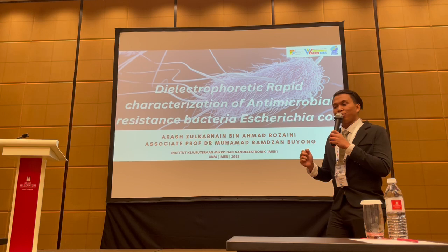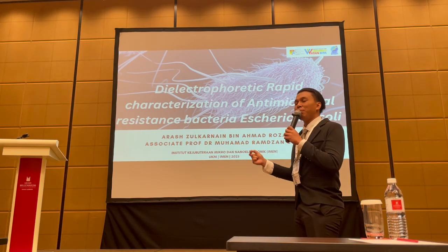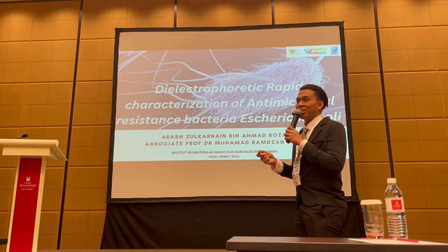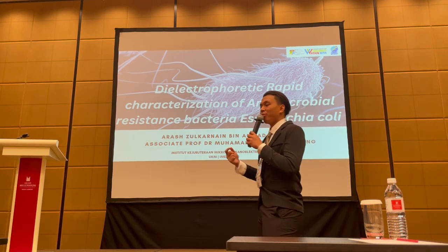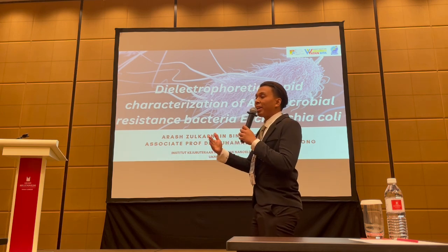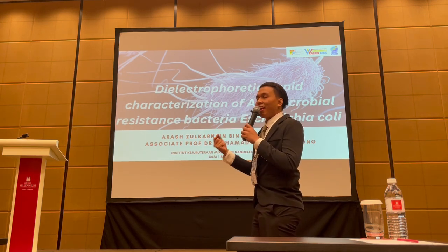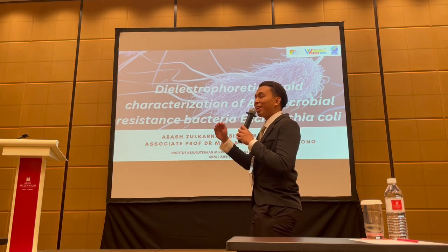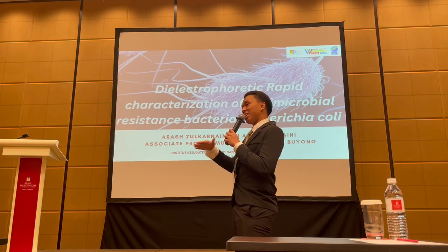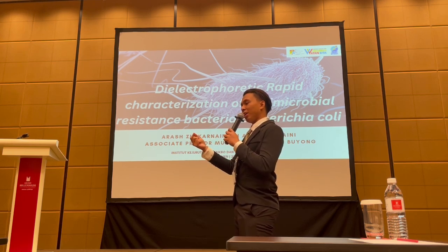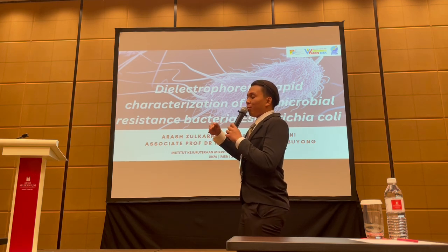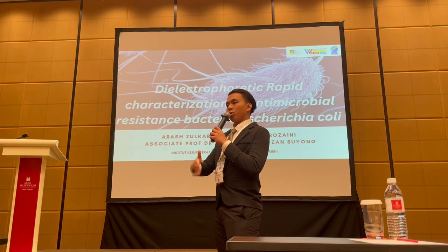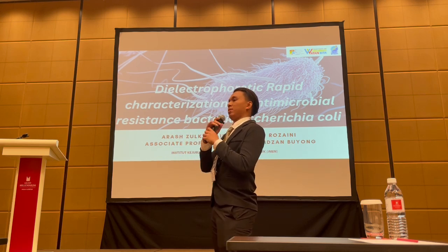When it comes to the inter-electrode gap, it doesn't change any DEP response, but it contributes to the electric field of the device itself. We would like the highest electric field with the highest DEP force. So to maintain a lower voltage peak to peak, which is easier to access and easier for experiments, we chose the best inter-electrode gap, which is 20 micrometer, based on past dielectrophoresis research.